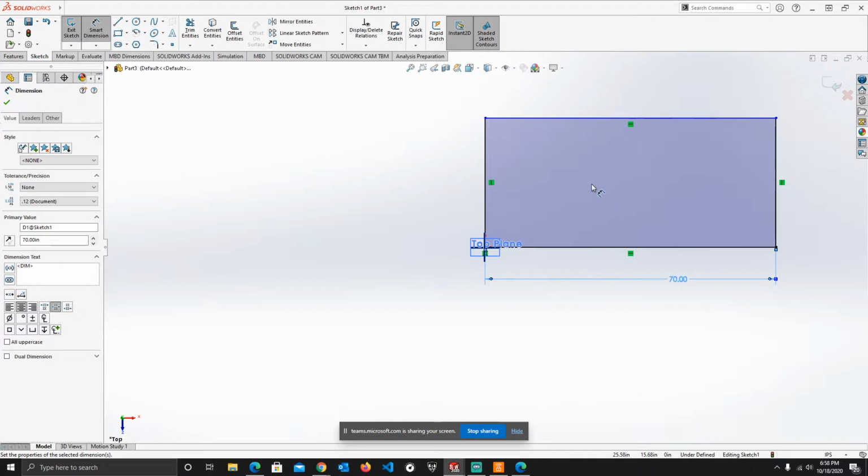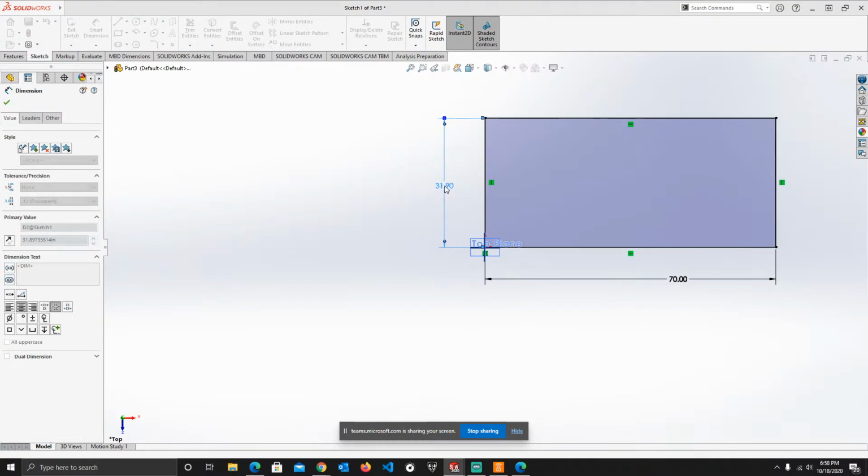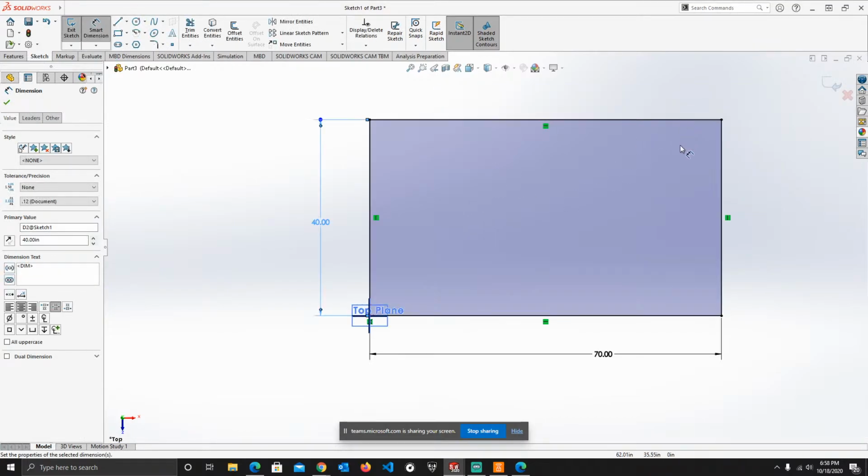This is probably in millimeters if I think about it, but whatever, we're gonna do it in inches. So the 70 inches, and then let's see. Okay, I look at that figure and the top left view tells me that it's a width of 40. Click here on this side right here. Let's make it 40. Boom. Fully defined. I define my bottom piece.